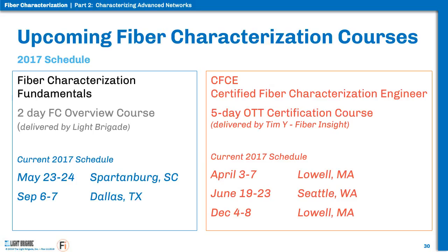I don't have any hard data on this, but if I've got something slightly oval, and the only difference between my core and my cladding is the change in refractive index when I'm building it, things are going to be pretty uniform all the way through the glass. So generally, if I have ovality in the core, I'm going to have ovality in the cladding as well.